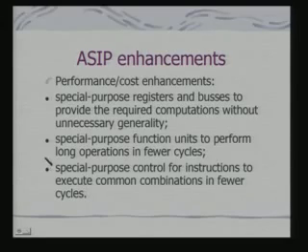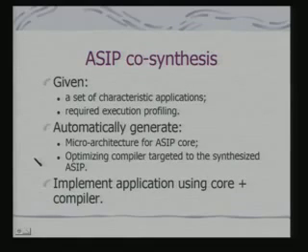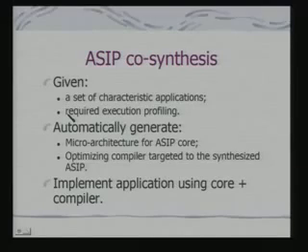Now, these ASIPs can actually be designed in an application-specific fashion. So the problem that comes up is what is called the ASIP co-synthesis problem. So you are synthesizing a processor. Given a set of characteristic applications and required execution profile, you would like to automatically generate the microarchitecture for the ASIP core and an optimizing compiler targeted to the synthesized ASIP.